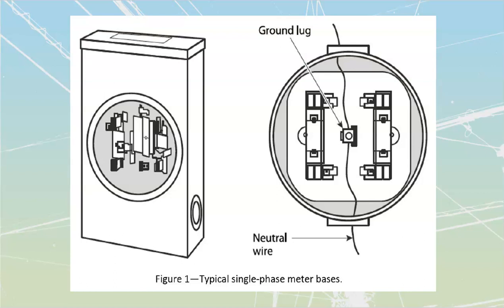Rule 6-104 talks about consumer services that are going to be the same voltage, where they're going to be allowed on a building to supply more than one unit. That's going to be no more than 4. And this is why, when you take a look at any of these quadplexes, they're limited to 4. You'll see no more than 4 together, and then there's a break, a little bit of green space, and then they'll have another 4 together, and then there'll be another break.